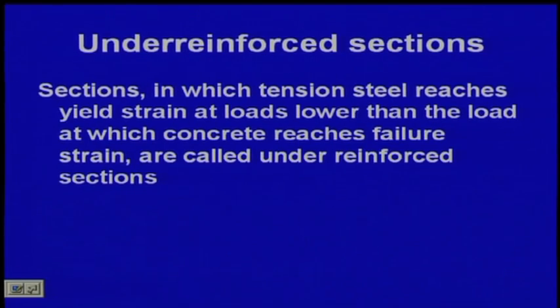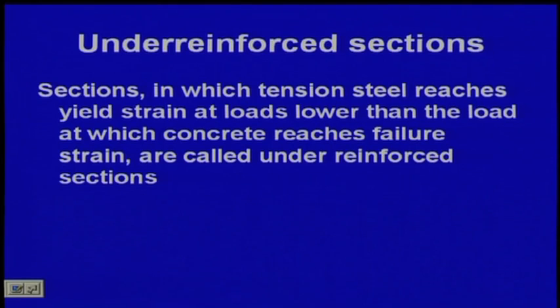In this case we can apply the load, and we shall stop when we measure the strain in the steel and find it has achieved say 0.0038 for Fe415. We can measure the strain and find 0.0035, and then we can stop there. Maybe the concrete has not reached that value, and that one we shall take as an under reinforced section.